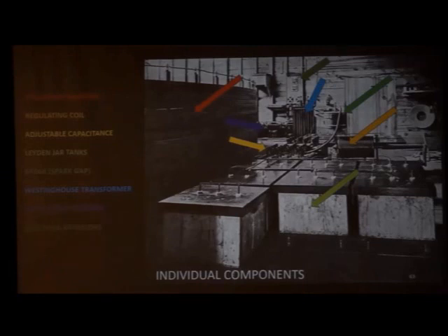That's how he sets his frequency. There's an adjustable capacitance. That's the brighter yellow. You can see all those knobs sticking up out of one of the tanks. There's two of those tanks. That's how he switches the individual Leyden jars in and out to get the final capacity. So that part of the setup there, the coil and the knobs on the capacitors, that's his frequency control.